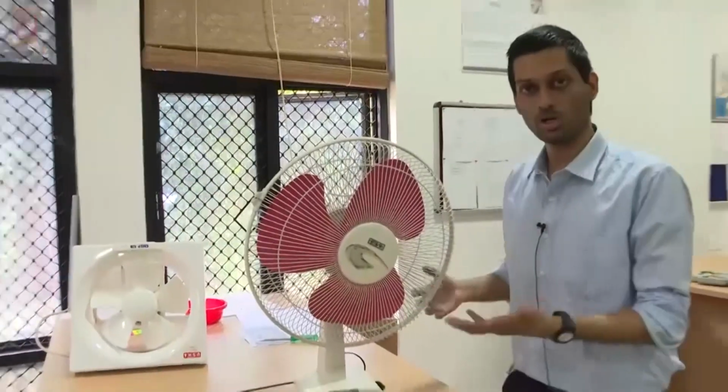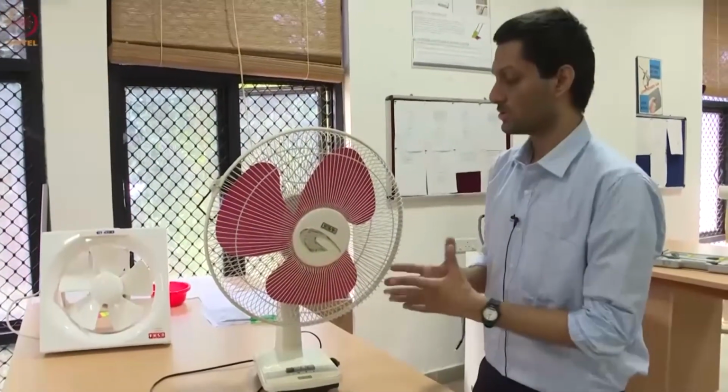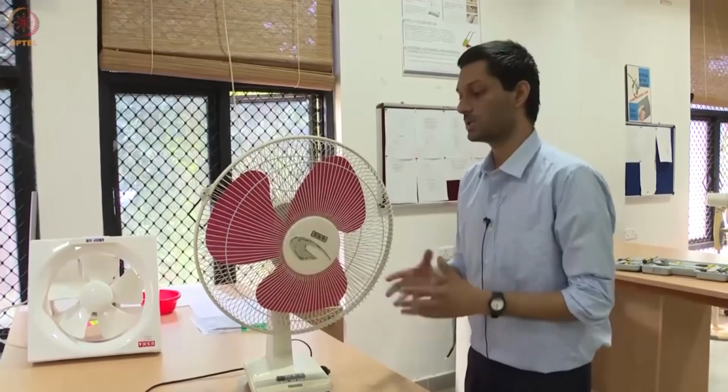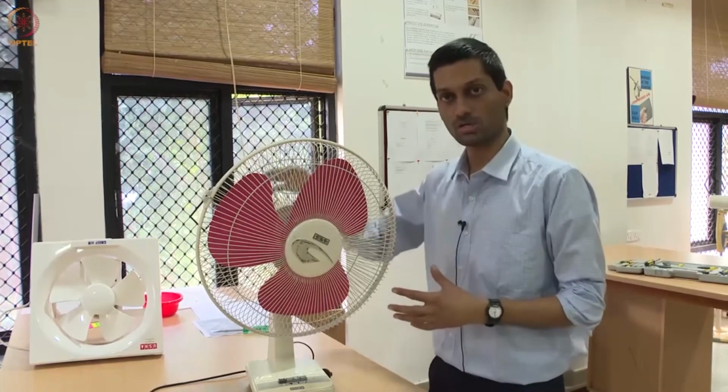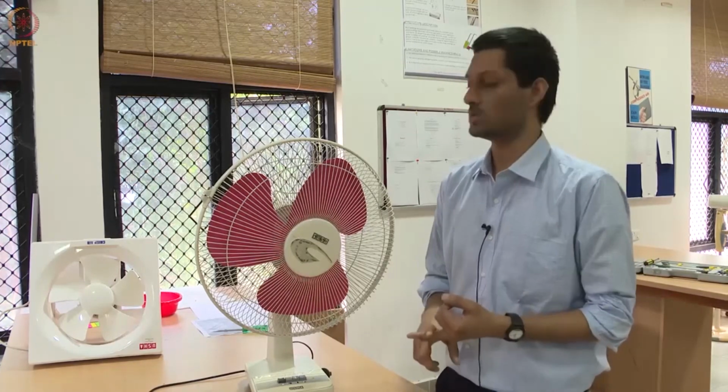So this is a slightly older model, right? It's a 3-bladed design that's quite prevalent, used in all our homes. Typically we have an AC induction motor, what we call a squirrel cage induction motor, a single phase motor that is capacitor start and run. Basically, any single phase motor is not self-starting, right? You need an additional starting winding.